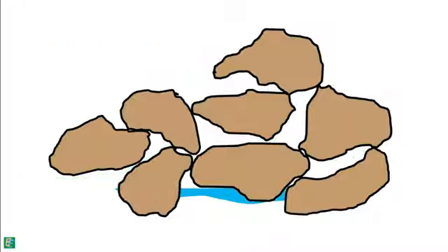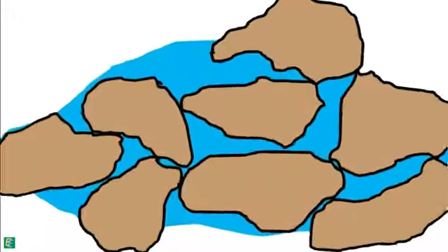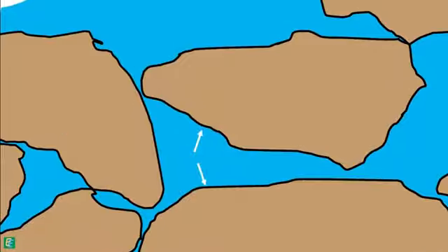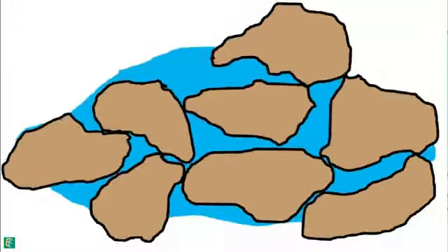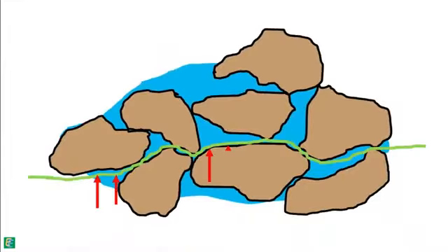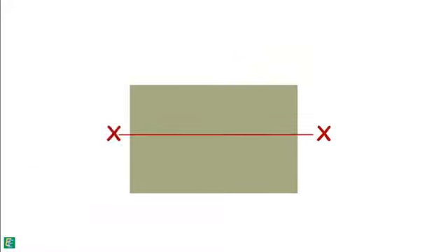The water filled in the voids of the soil also exerts pressure on the soil grains in all the directions as Pascal's law suggests. This pressure exerted by the pore water is called pore water pressure. This pressure exerted by water also supports the stress due to the weight of overlying material. This pore water pressure can be easily measured by inserting a standpipe or tube inside the soil at the location where we want to measure the pressure.